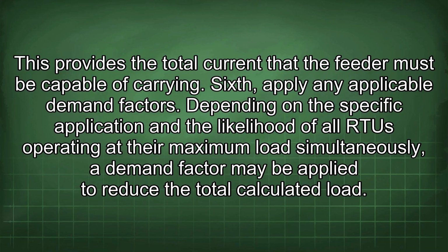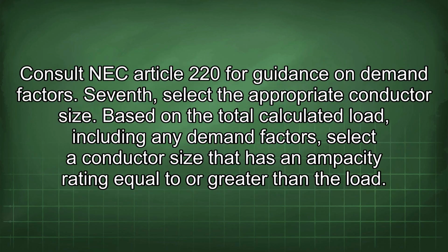Sixth, apply any applicable demand factors. Depending on the specific application and the likelihood of all RTUs operating at their maximum load simultaneously, a demand factor may be applied to reduce the total calculated load. Consult NEC Article 220 for guidance on demand factors.